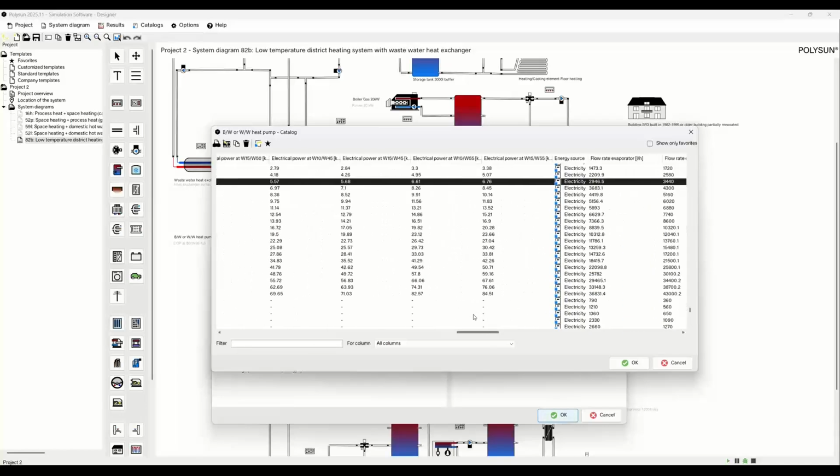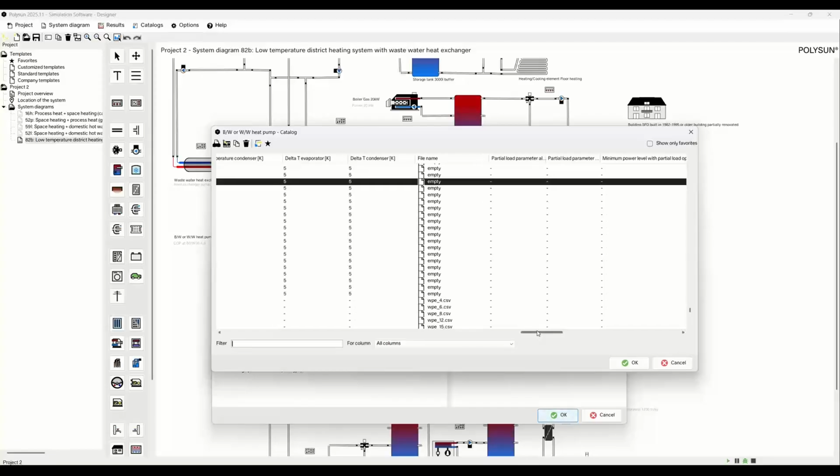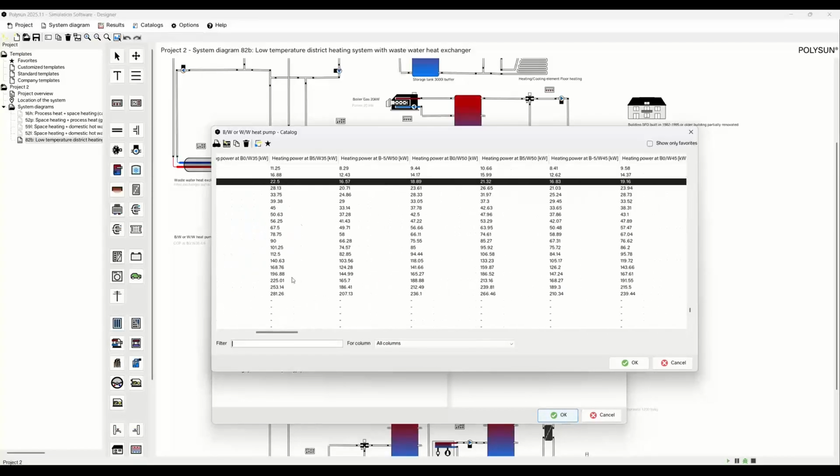And if you want to be more individual, you can also just enter the file name here as a CSV file. So then you can define the temperature pairs yourself. For example, really high temperatures or also partial loads can be defined there. So in Polysun, what matters for the behavior of the heat pump are the specifics included by pairs of heating power, electric power, and temperatures.